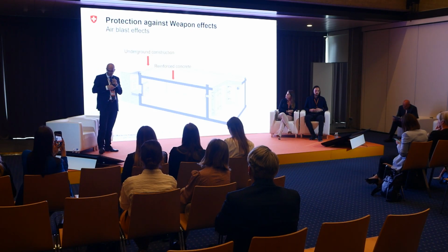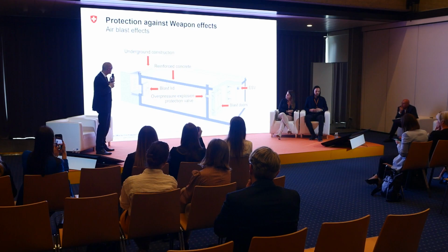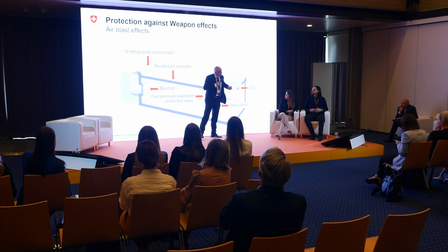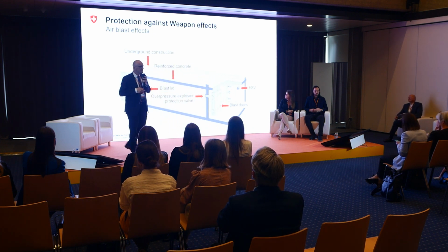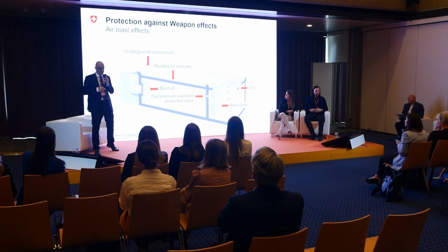So, as I said, underground, reinforced, we have blast lids, so the whole thing is airtight besides the ventilation system. We have overpressure valves and we have explosive protection valves here, which have to close within 4 milliseconds when the air blast comes in, so that the inhabitants are protected.